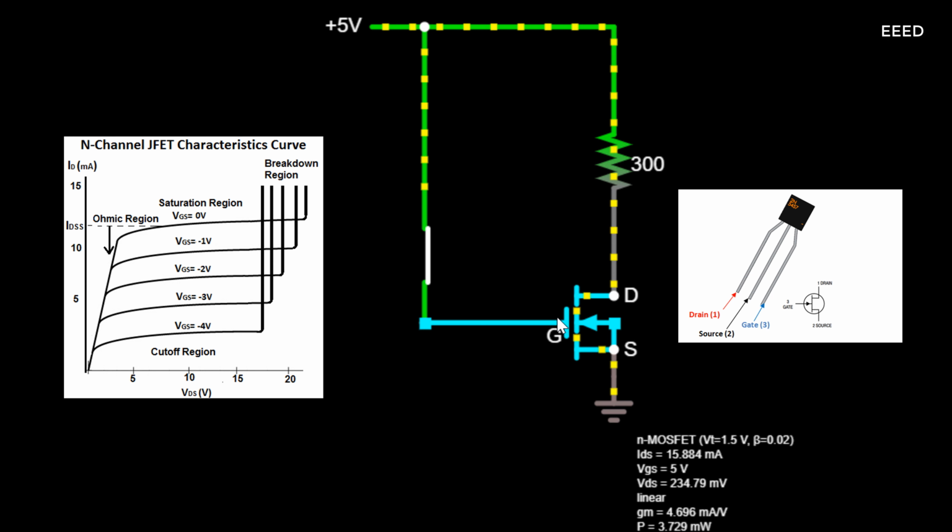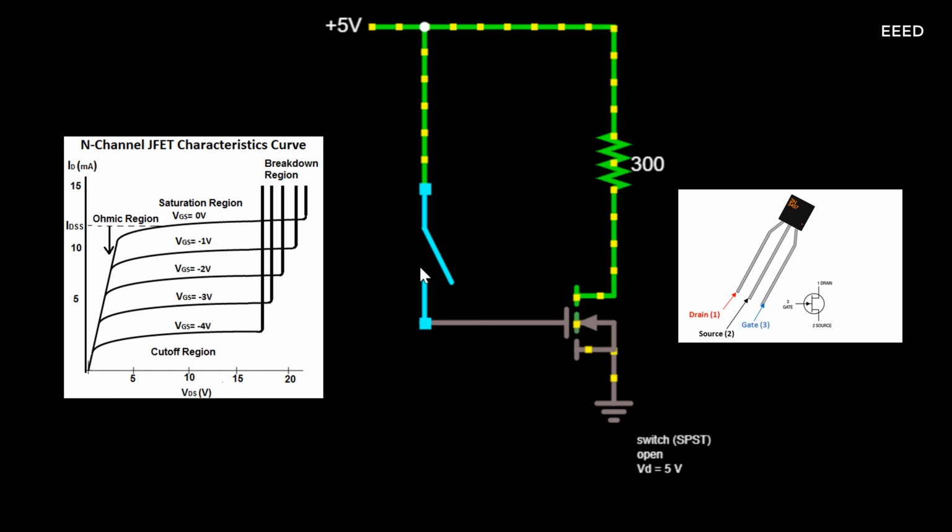The big point is that an N-channel JFET turns on by having a positive voltage applied to the drain terminal of the transistor and ideally no voltage applied to the gate terminal. The transistor circuit shuts off by taking in a negative gate voltage, VGS, greater than about -4V or so.